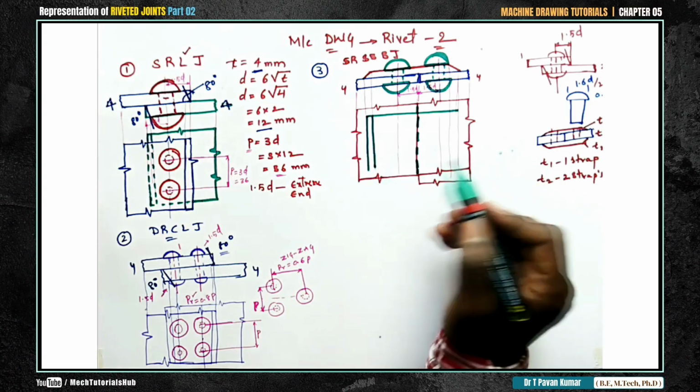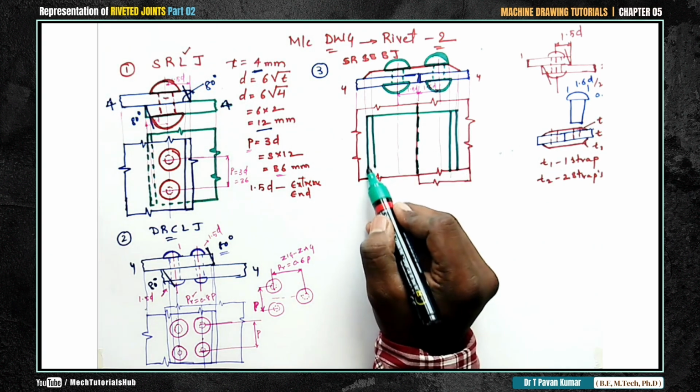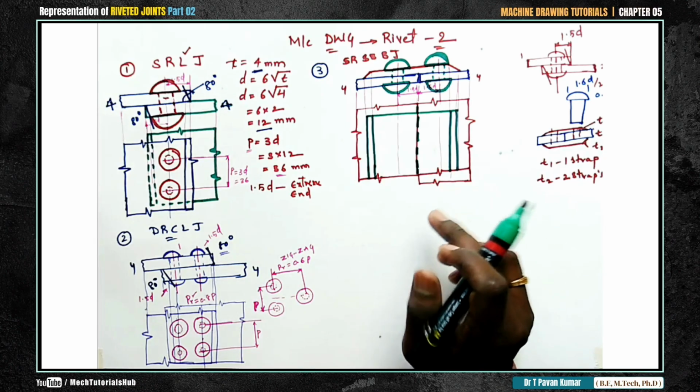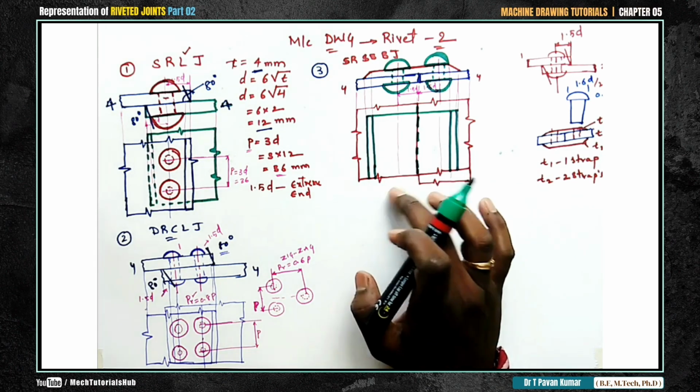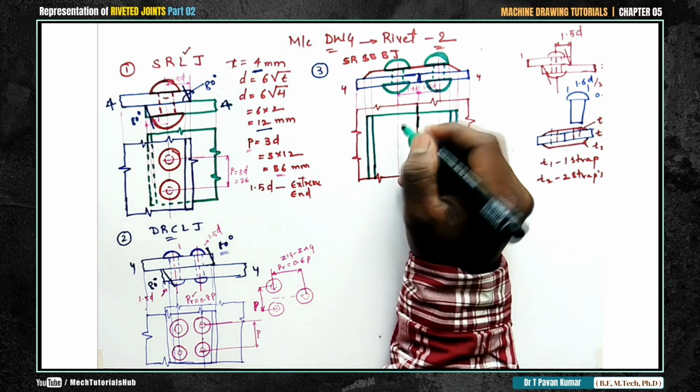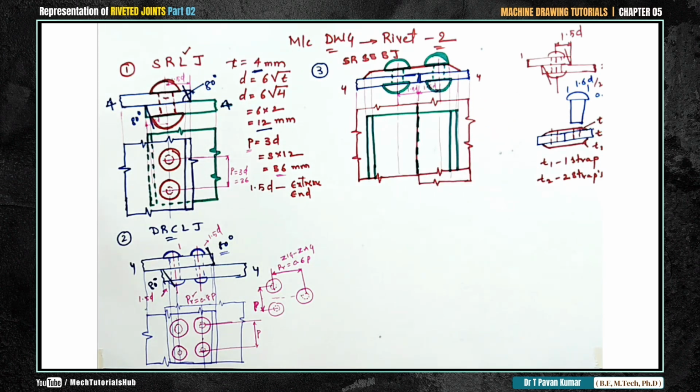Similarly, the other side also I'll try to continue. Okay, join with this. So this green one is your strap, which is aligning both sheet number 1 and sheet number 2. Okay, after this again in a similar fashion try to place rivets D, 1.6D.